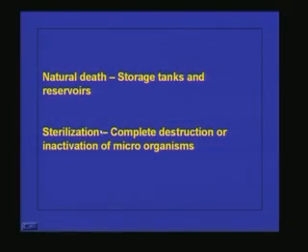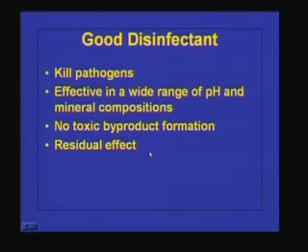What we do there is, we allow the water to stand for a long time under sunlight, for example in oxidation ponds. The oxidation pond is exposed to sunlight, and sunlight has UV radiation. Because of that, the microorganisms are getting killed. And I have already told that there is a distinct difference between disinfection and sterilization. Sterilization is the process in which complete destruction or inactivation of microorganisms takes place, and in disinfection, only pathogenic organisms are killed.